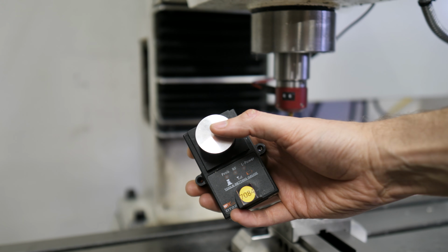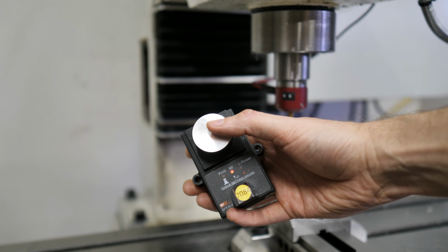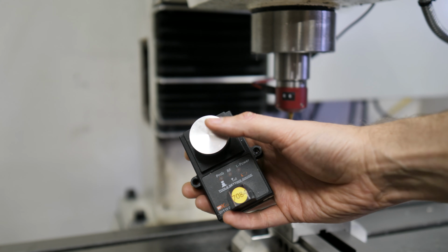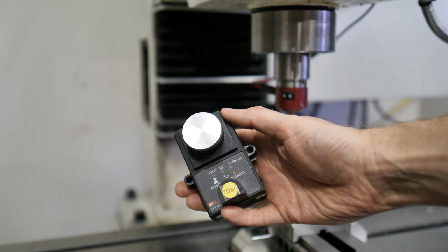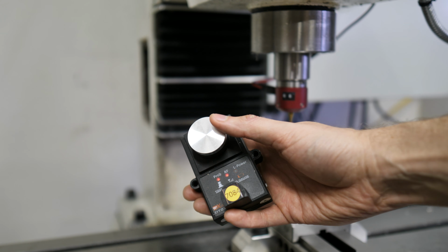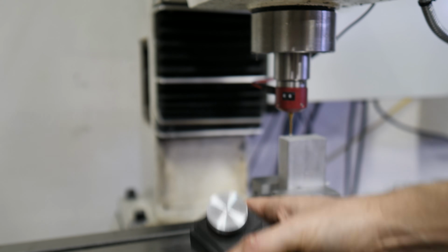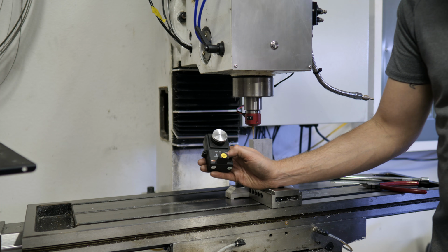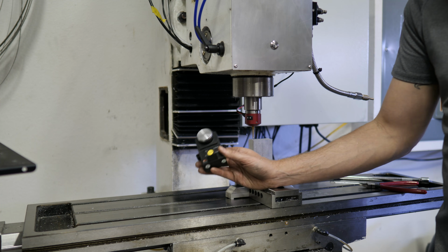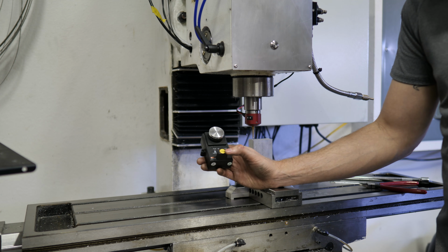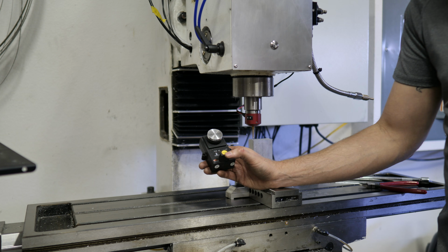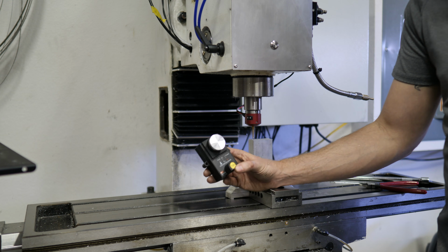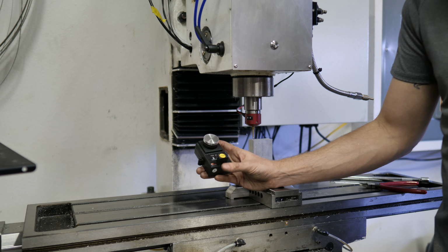When you click it the first time, it'll power up itself. It'll tell you that the probe is being clicked. The RF light here tells you it's communicating with the receiver. The low power light will come on if the battery is dying. It'll give you ample warning. When the battery finally does die, it is smart enough to recognize that it's not communicating with this anymore, and it'll activate your probe and you're likely not going to crash into anything.